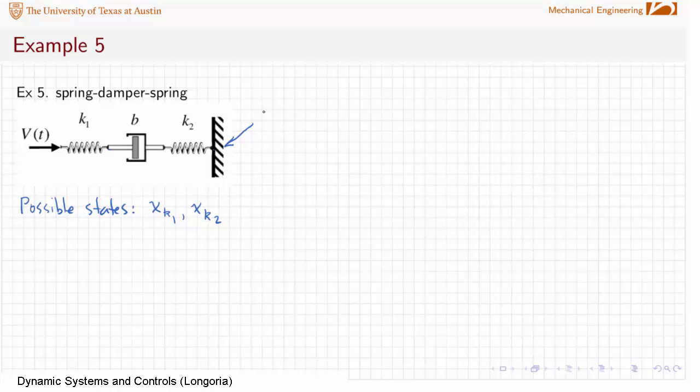And remember, we were also interested in what is that force on that wall? So again, that's one way to start thinking about the system. Remember, when you have ideal springs and dampers, these transmit force across them, and so we begin recognizing just from studying the schematic here that the force on all of these elements that are mechanically in series have to be the same.